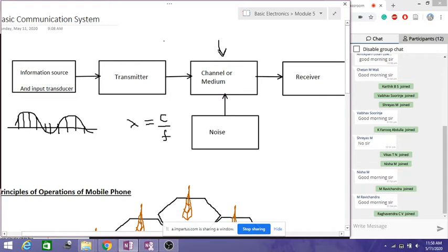So when we are transmitting this signal, whether through wireless, an antenna, optical fiber, or copper wire, there will be noise added to it, because whatever we transmit gets added up with additional noise from the environment it goes through. If we talk about wireless, the signal is in electromagnetic form, traveling from transmitter to receiver, and along with that there are other frequencies that exist in free space, which act as interference to the signal we have transmitted, so that acts as noise. In the case of copper wire also, it might be power noise or some kind of crosstalk or impedance, or the high electrical power lines, which also introduce interference in the channel.